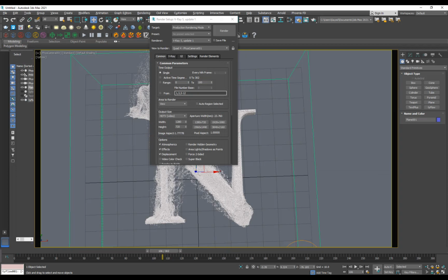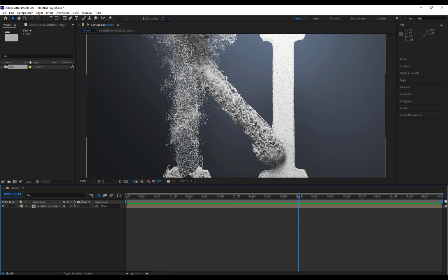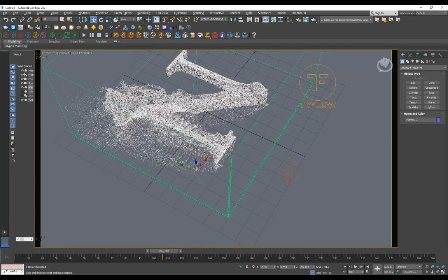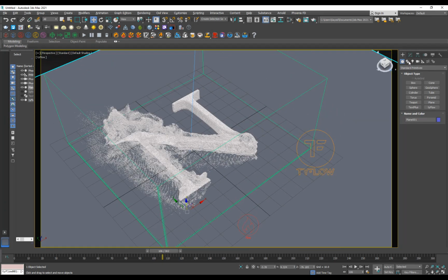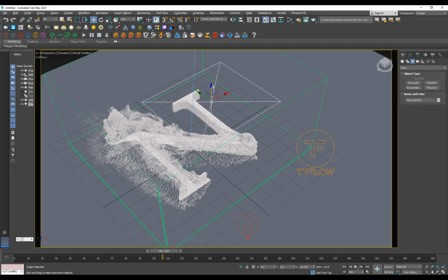And then in order to get this really cool lighting, especially if you look here, we got a lot of nice shadows and details. So I've added 3 lights, one from each side and then from the top. So what I'm going to do is go back here into the perspective view, and I'll just add a V-Ray light, just like that, and just rotate it. Hit A to turn on angle snap, and just rotate it like 90 degrees from this angle.